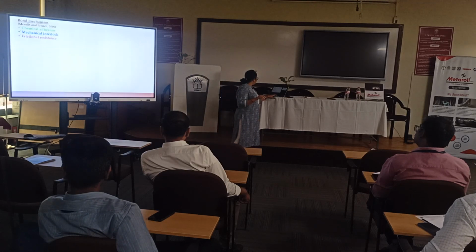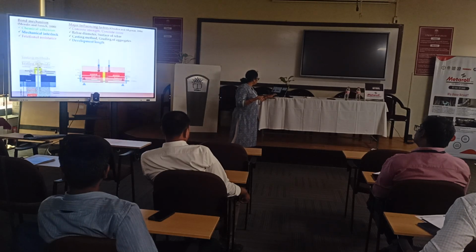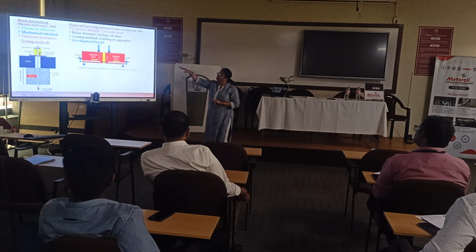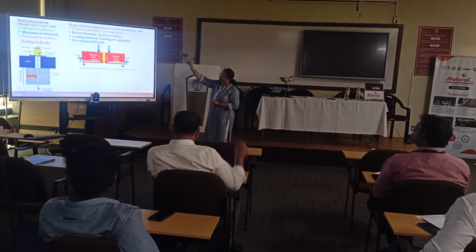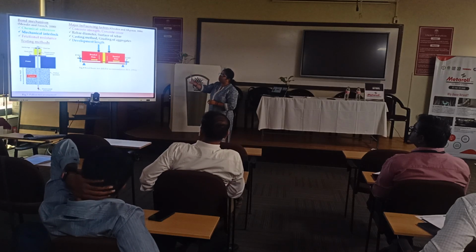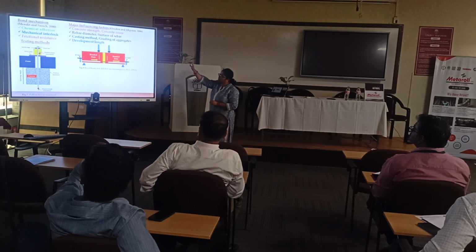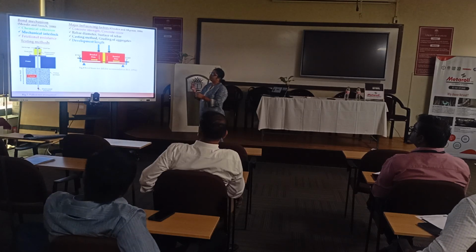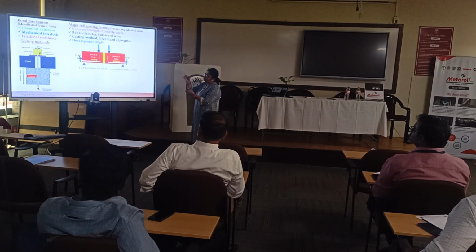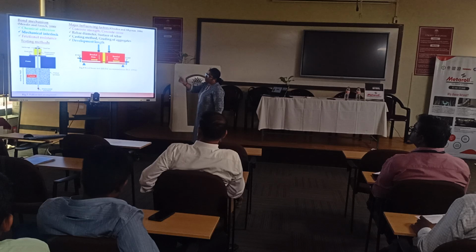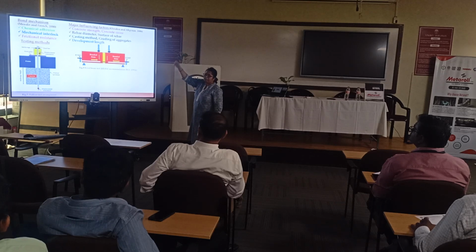Now, what are the things we do in testing? If you look at how it has been measured throughout history, there are the three factors I mentioned: chemical adhesion, mechanical interlocking and friction. But mostly we have two kinds of test methods. One is called the pull-out test, where the steel is completely embedded in the concrete form, and we try to pull the steel from the top.